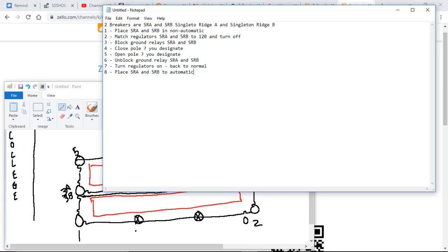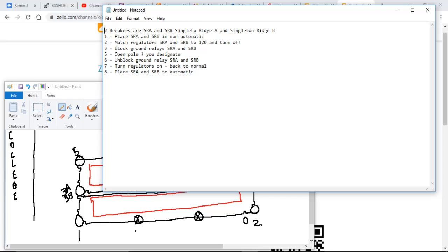You're going to get a switching order that has a specific number to it. We'll say, what's today? 1, 2, 2020. So it's 12/2/2020. You're going to get a designated number, -1. So they're going to go through the course of the day. The next switching orders are 2, 3, 4, 5 as they go on. You're going to call in and tell them, I'm ready to begin field switching order 122-2020-1. And they're going to repeat that back. I understand you're ready to start switching order 122-2020-1. You're going to say that's correct.